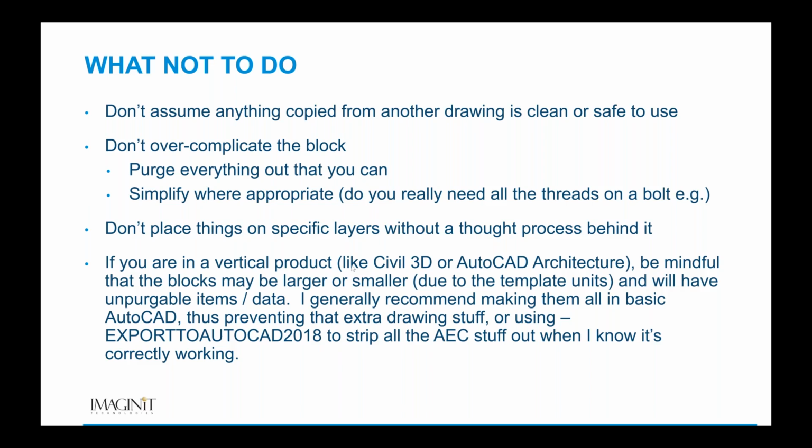So this is why I point this out. I have a lot of people who create everything in Civil 3D and can't understand why their drawings get so large, because every block you're inserting is a megabyte minimum because it's built off a template that has all the styles, things like that.